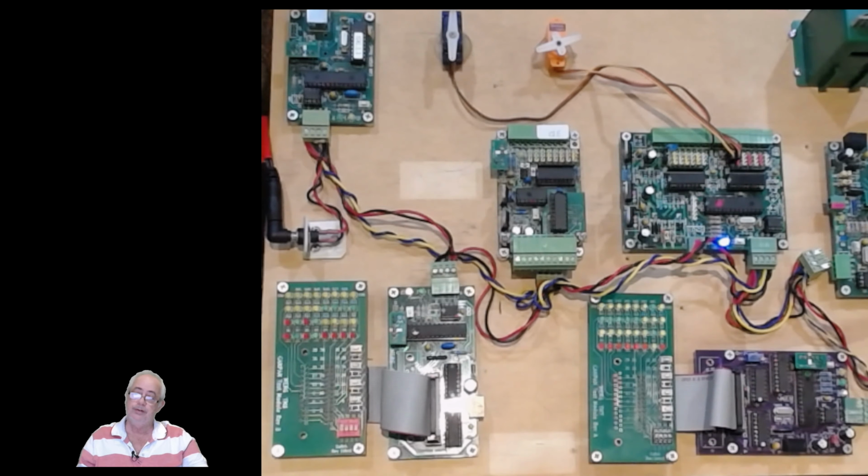We don't have feedback for our point, but we also don't have a switch to control it. Now, the usual workflow that you can think of here is I press the switch, it moves the point. The movement of the point will generate feedback from the start, the middle, and the end, and I'll use those feedbacks to control the LEDs on the panel and the output for the frog polarity. So probably at this stage, it wouldn't be a bad thing to make the switch make the point move.